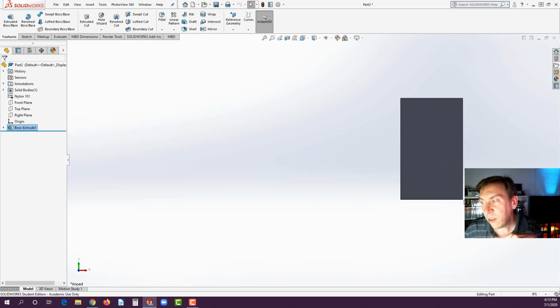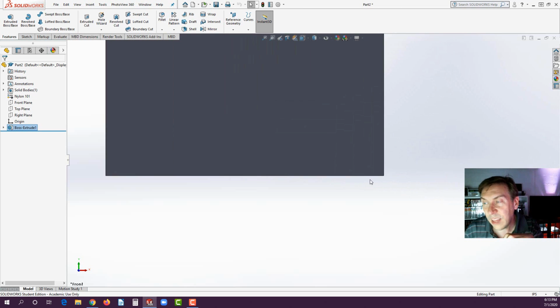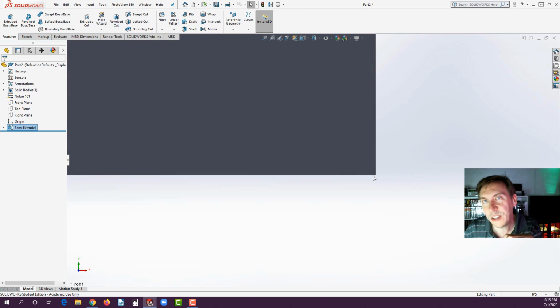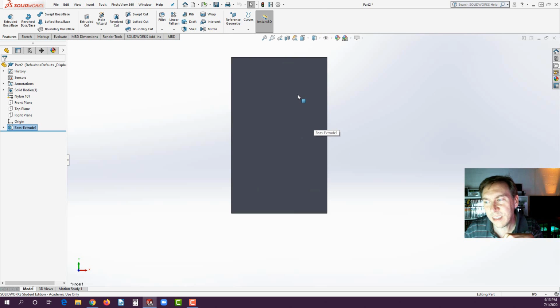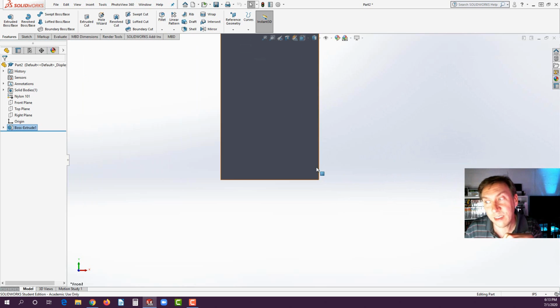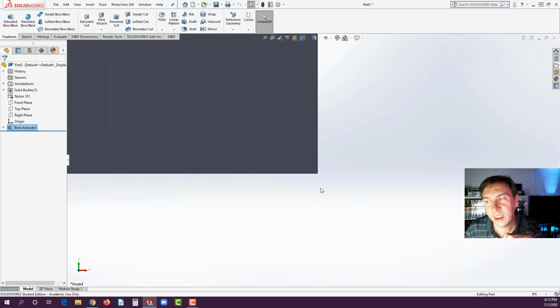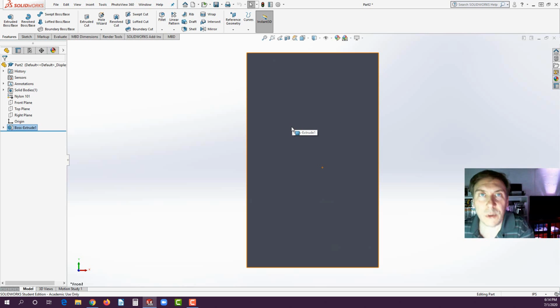Stay and hover over that pointer no matter how far or how close you zoom, and it will allow you to zoom to that region. So get used to that. A lot of people don't realize the functionality that you have there. You can focus in, like a focal point in an area. F on your keyboard again, zoom to fit.